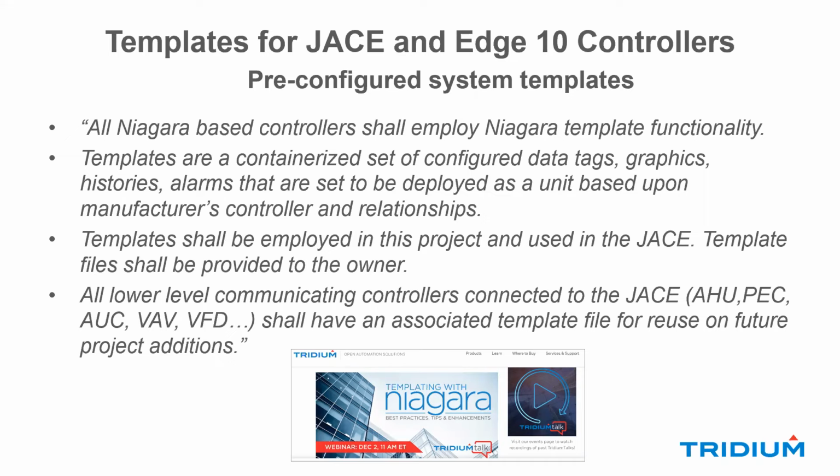So think about a VAV box controller from Johnson. If there's a template built for it, when we go out and do the learn, the SI says, that's a Johnson's number such and such, boom, apply this template to it, and it's got all the information already there. Now, those templates might already be built in a library that the owner has, or you might have to build new ones for the project. But I really encourage in specifications that they require the SI to build these templates out so that you can reuse them on later jobs.